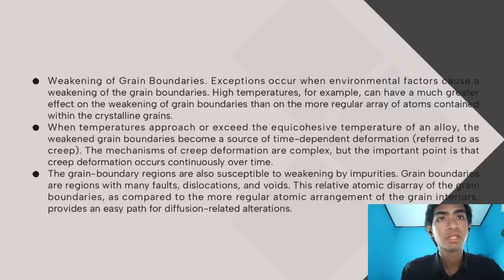Thus, continuous deformation caused by creep can lead ultimately to creep rupture. Creep and creep rupture can be the limiting factor in design of adequate section size for application at elevated temperature. In this case, creep stress and the stress to rupture describe rupture strength at high temperature and are important properties.